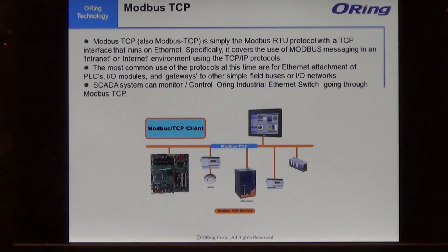Modbus TCP is a very commonly used communication protocol in the industrial field. With implementation of this Modbus TCP protocol, Orange Ethernet switch can be configured, monitored, or controlled by any SCADA system on the Ethernet that has Modbus TCP protocol supported.